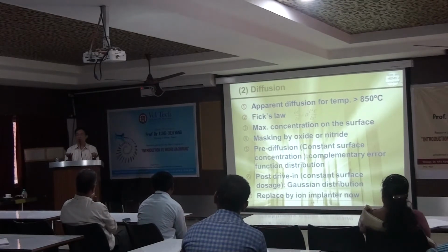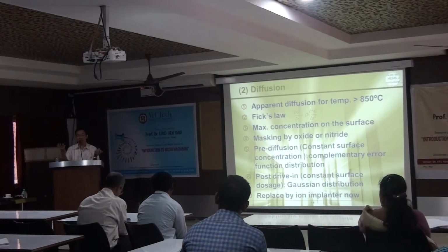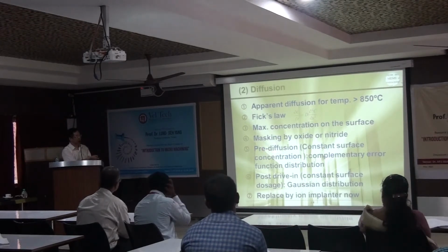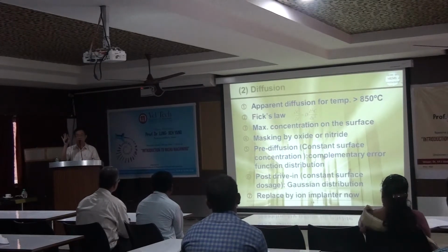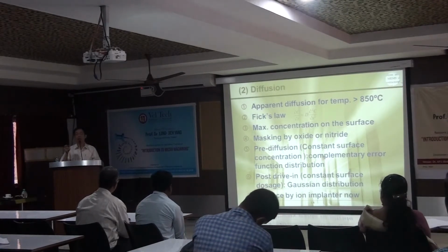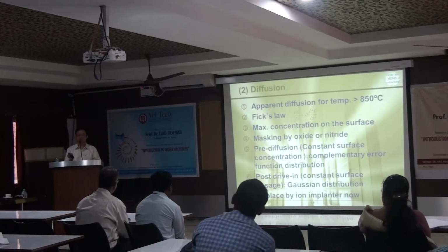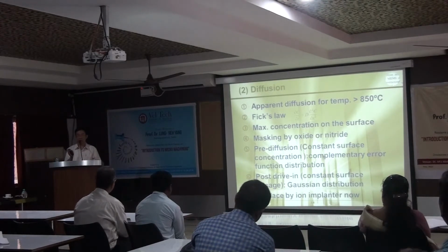So we need to wait for the cars to drive away. Otherwise, the traffic jam stays there. Similarly, if pre-deposition encounters a saturation phenomenon, you should wait. But how to wait? It means you must stop the dopant release.